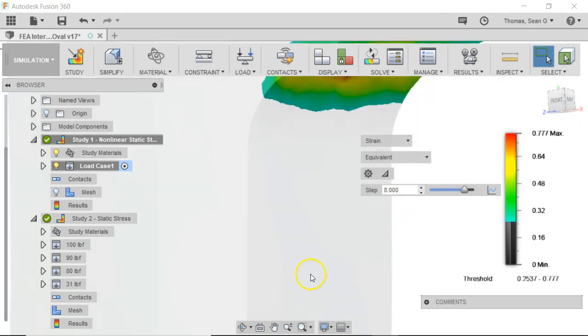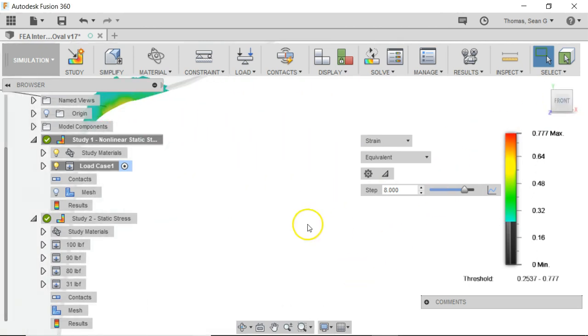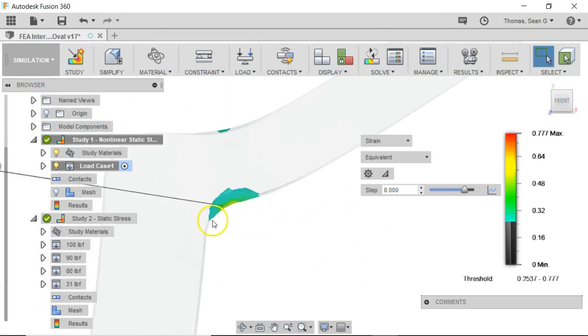not right away. Now, if I go to the 80-pound mark, step 8, I'm starting to see appreciable penetration into this thickness, right? This is probably 25% of the total thickness. So if I were interpreting this, I'd probably say 80 pounds is where I'd expect to see crack initiation. And as soon as that crack initiates, if the load's maintained, we're going to see catastrophic failure.